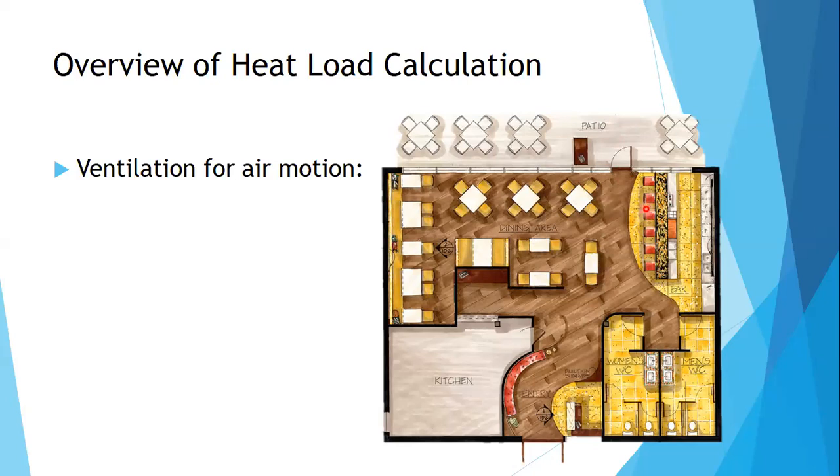Now, like what Engineer Gabriel said, for air conditioning engineers, this is kind of a problem, because when you let air go out, you're basically wasting money or throwing away money. But when you let air come in, it will give you problems. Why? Because the outside air and the supply air of the area are too far apart, meaning condensation may happen. When you keep introducing untreated air from outside, it will have contact with your supply air, which would be at low temperature. Condensation will appear.